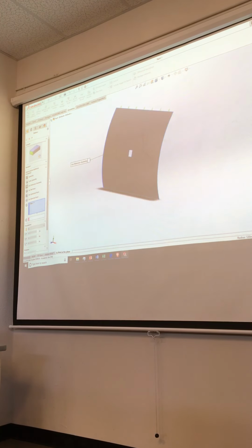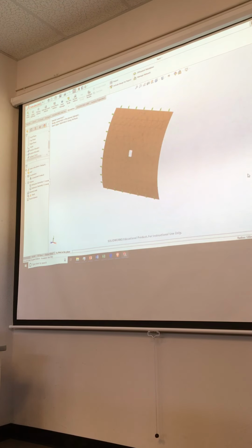Okay, so a reference, right? And we could do a couple different ways here. We could go pick a plane to do a reference. Just as easily, I could go back and pick this, get my polar coordinates, except now I want to fix it in the axial direction. That's the direction I want to fix it in. And then I'm going to take out the other rotations. Okay. That's pretty good.